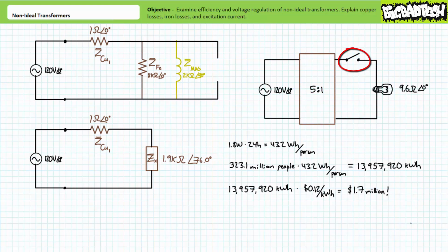As currently implemented, opening and closing the switch only cuts current in the secondary and not the primary, leaving the non-ideal transformer and all its modeled inefficiencies, including leakage paths in parallel, still active. A far better re-engineering of this circuit might be to relocate the switch to the primary side, effectively cutting the head off the snake by completely depowering the transformer in addition to the load in the secondary.